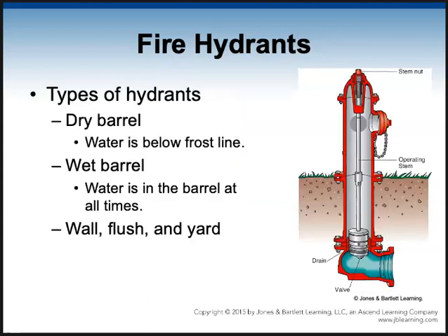There's basically 2 types of fire hydrants, dry and wet. But there are some other versions out there. There's wall hydrants, flush hydrants, and yard hydrants. But most of the time, we're going to see dry barrel or wet barrel. The dry barrels are going to be for those areas that have colder temperatures where they can get freezing in the pipes. So they want to make sure that the water is below the frost line.